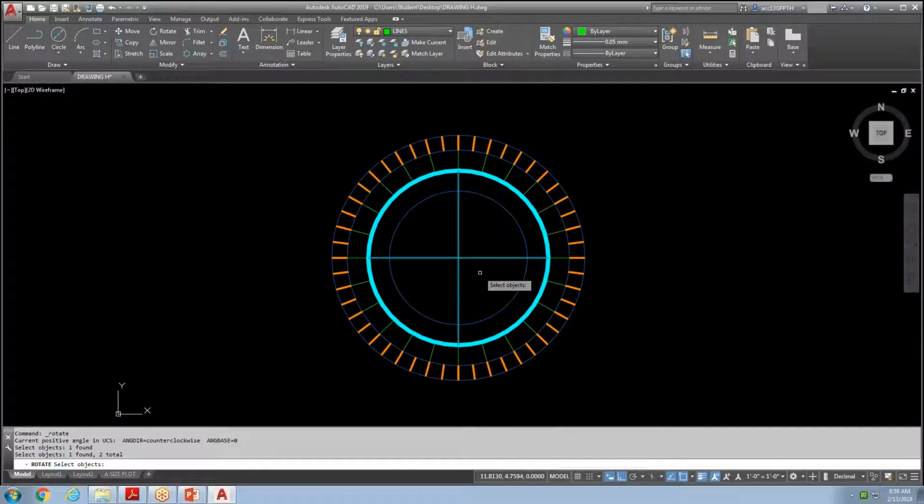I click on those, and now I'm in the AutoCAD stare down. It wants to know, what do you want to do now? Well, I have to tell it to go to the next prompt. So again, I right-click my mouse. I hit my Enter key or hit my space bar to get the next prompt. And the next prompt is specify a base point.